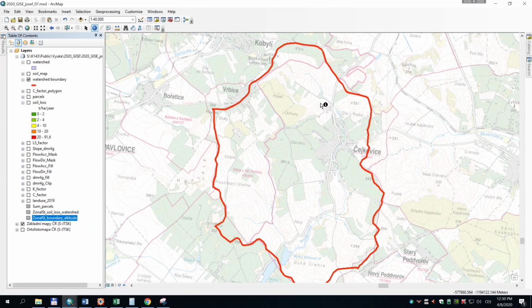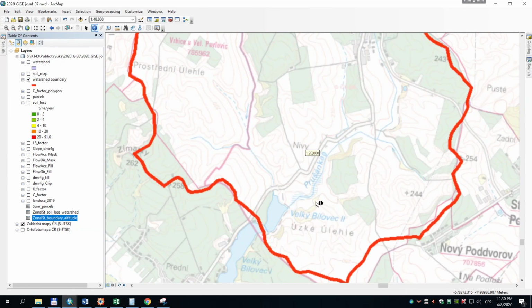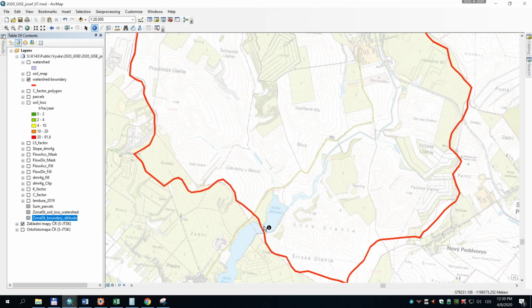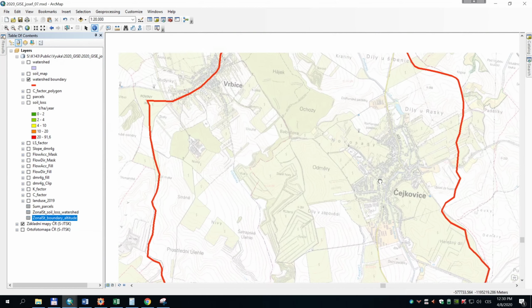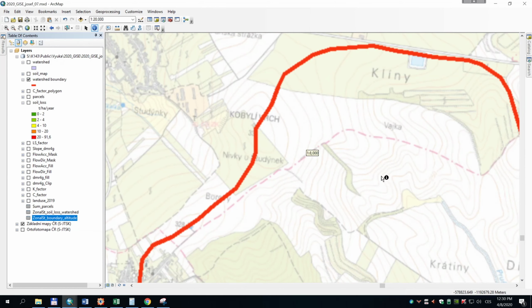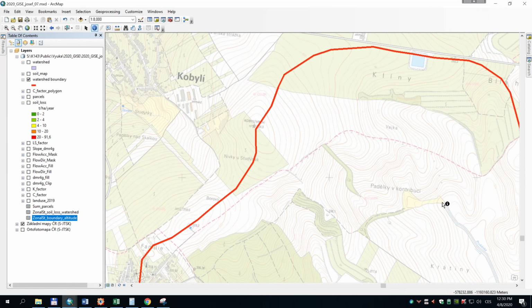Okay, there are tools how to estimate this by GIS hydrology tools, but it's for longer evaluation. So right now, maximum stream length means from the outlet through the river net up to the top of the hill. So we are not ending over here, but we have to go to the top of the hill.